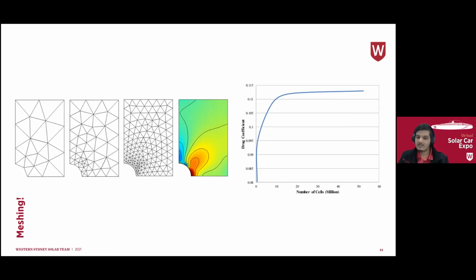There are two main factors of the mesh that need to be considered. One is the quality. In simple terms, you want as uniform of a mesh as possible. You want cells that have very even aspect ratios. You don't want very large cells next to very small ones, rather than slowly transitioning from big to small over many layers. For CFD, like I mentioned, you want very specific boundary layers of cells that is right for the part that you are simulating.